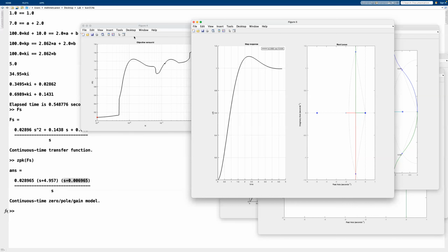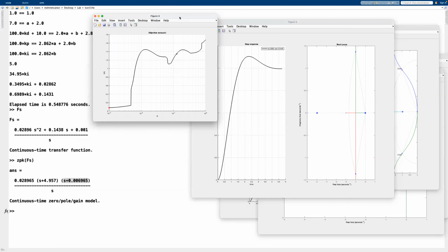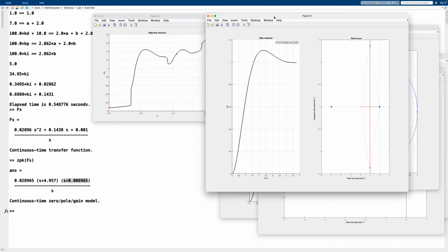But of course, that's not most of the time the case. Pole zero cancellation is not always optimal, and probably not optimal at all. But this is a very special case to indicate that pole zero cancellation might happen and might do the trick. The only issue that we would have with this controller or this setup specifically is the fact that the pole zero cancellation might not happen.